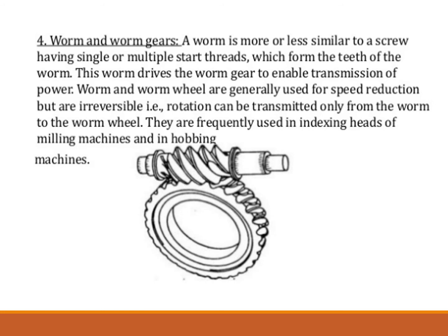Ratios as high as 70 to 1 can be made with a worm and worm gear, whereas other types of gear cannot easily give more than about 6 to 1 in one pair. The teeth on the worm gear are helical and conform with the helix angle of the tooth on the worm. The helical tooth on the worm is a form of thread similar to an acme thread.